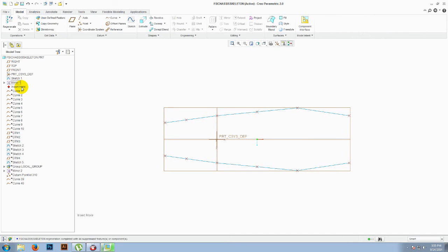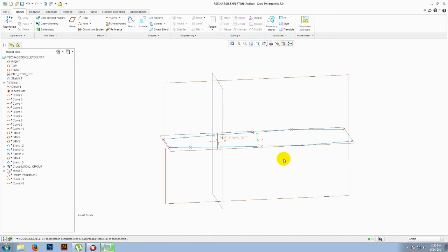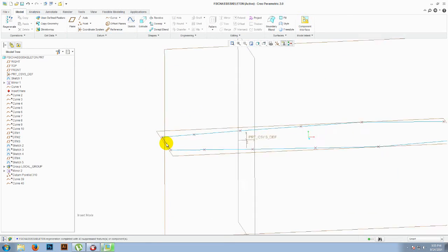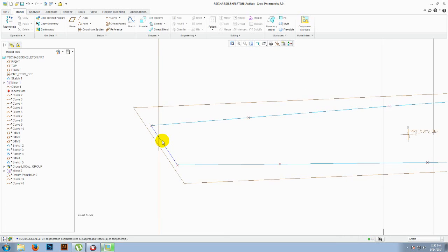The next step is actually a mirror, and then I started using 3D curves, that is the curve through points option in Creo. That is up here, or rather you can find it in the datum drop-down list. It actually creates a curve between 2 points that you select.